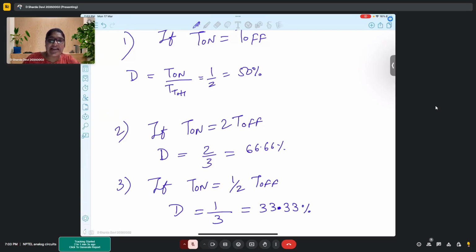So we discussed. I analyzed that problem. What I found out is when you have the same values for the resistors, you don't get anything in the numerator. You only get something in the denominator. So getting the required phase condition is not possible in that particular case. But when you have different values for resistors, you get some factor in the numerator and some factor in the denominator.